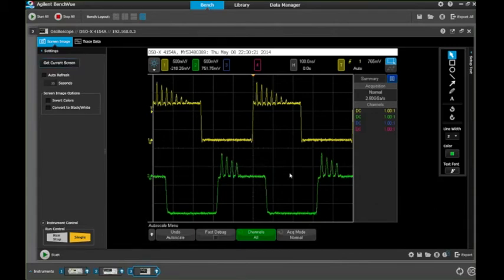So what does that mean? That means that DDS generators by themselves pick which points they're going to skip. This is actually very frustrating for engineers, because you cannot predict which points will be skipped by that DDS technology. So if you need certain characteristics on your waveform, DDS technology is going to be a little bit limiting for you, in that it's going to skip points and it's going to do it unreliably, unpredictably, let's say that.